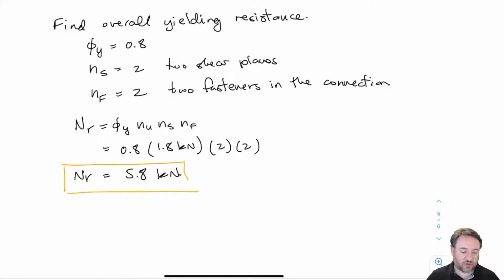In this connection, since both sides of the connection are timber, we have the beam on one side, and then we have two braces on the other side. Basically on the other side of the load of the bolts. So the bolts are being pulled one way by the beam and in the opposite direction by the two braces. Those are the two sides of the connection, and we have to check both sides separately. I'm going to start with the beam resistances, and we'll start with the row shear resistance. After that, we will do all the brace resistances. So let's get started.